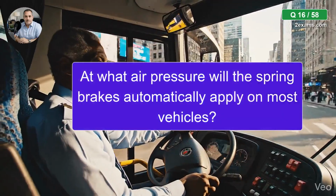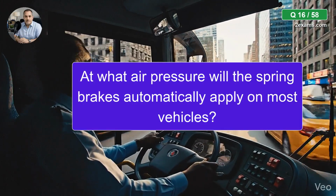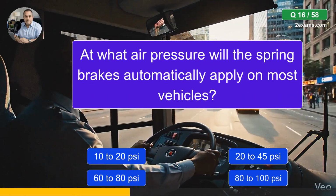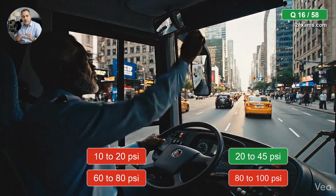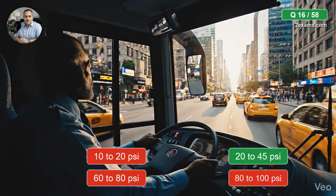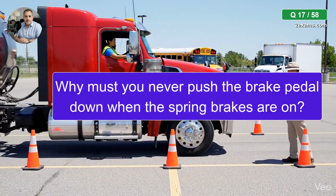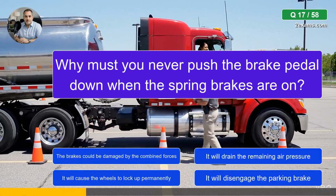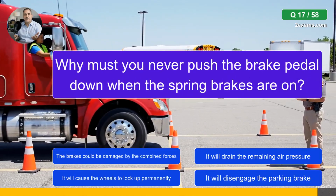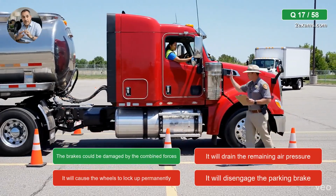At what air pressure will the spring brakes automatically apply on most vehicles? The correct answer is 20 to 45 psi. Why must you never push the brake pedal down when the spring brakes are on? The correct answer is the brakes could be damaged by the combined forces.